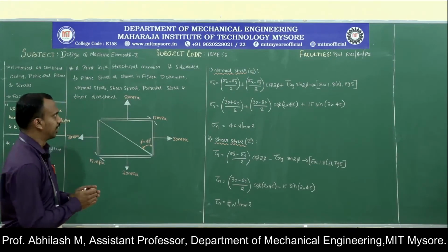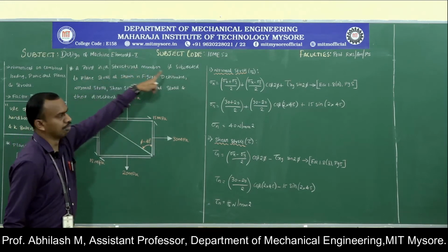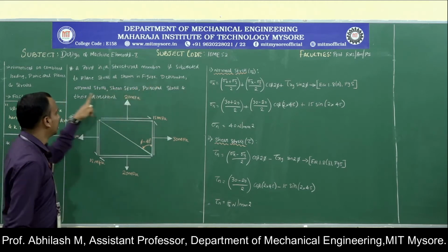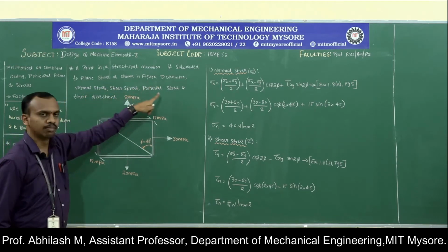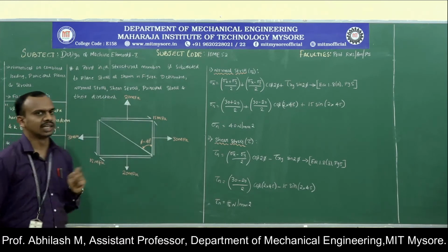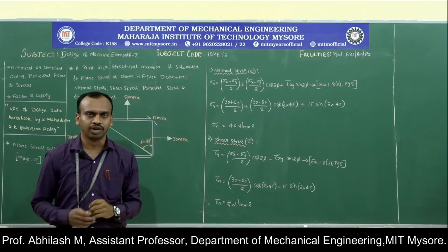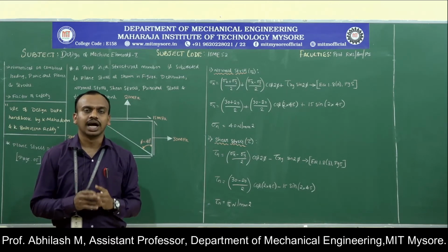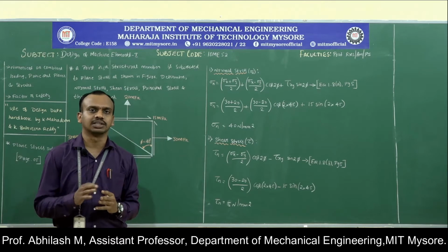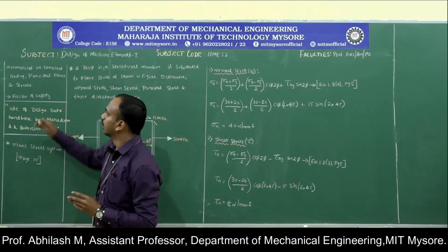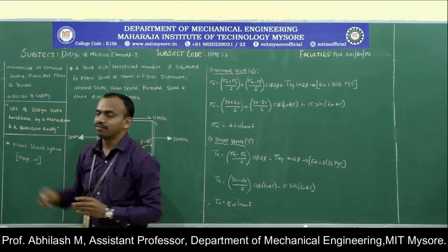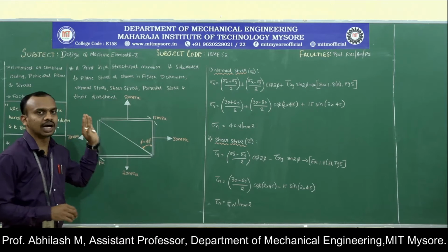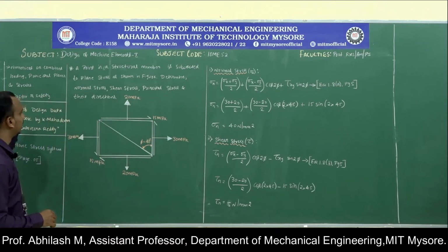Now, the next problem states that a point in a structural member is subjected to a plane stress as shown in the figure. Determine the normal stress, shear stress, principal stress and their directions. So far in the previous problems, we have taken a member subjected to loading conditions and calculated the maximum stress developed, and in the cases of combined loading we have understood the problems, whereas this particular problem comes under the heading of principal planes and their